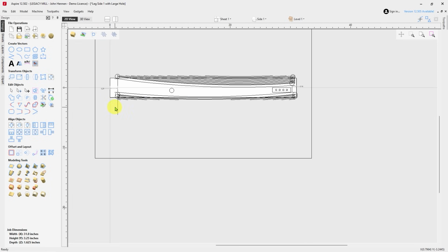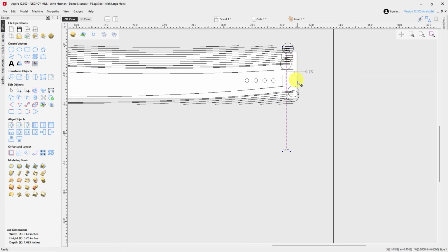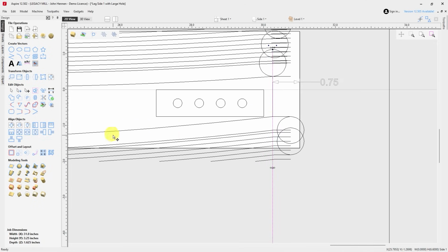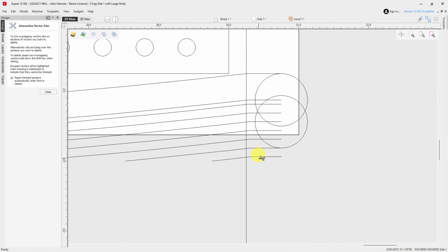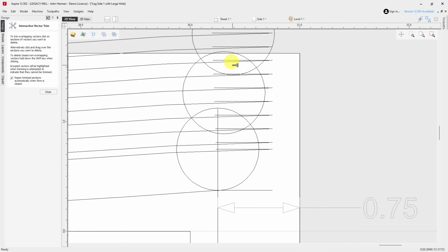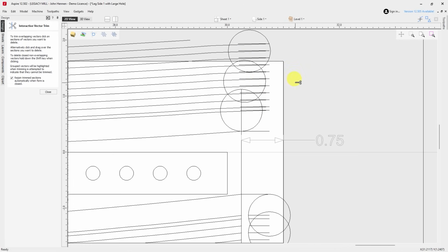And let's go ahead and do that on the other side as well. Let's just grab that same line and we'll snap it there. Okay. Use our scissors tool, trim. Perfect. Oop. If we take an extra one, we just gotta do a little Control Z, which is one of my favorite tools that there ever was.